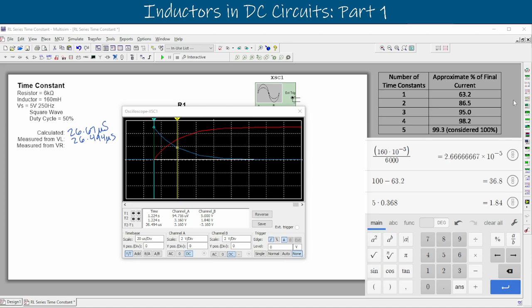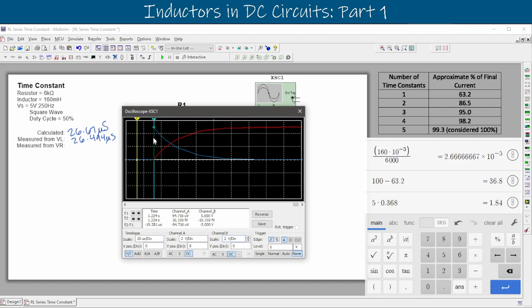Now we can reset this and go after the red one. We know that the signal starts in the same exact spot, where that red line also increased. We can click on here and see that when we move our T1 forward, we can look at channel A, and that's when it starts to increase right here, 77.46. We go back, it's at a microvolt. It immediately jumps up to millivolt right there, so we know that's the beginning. We go down, we are at the femtovolt. So that right there is where we want to start.